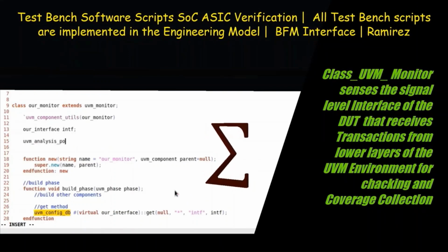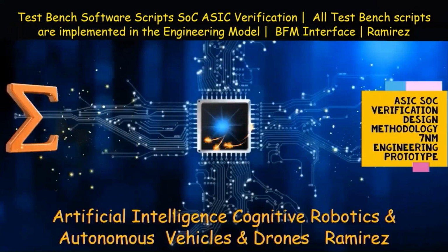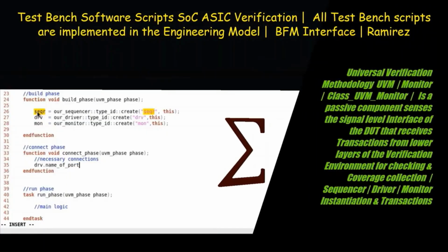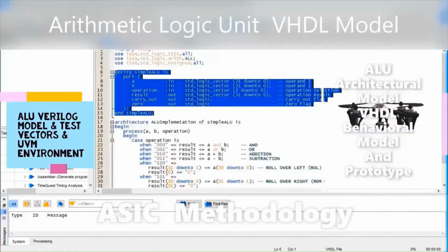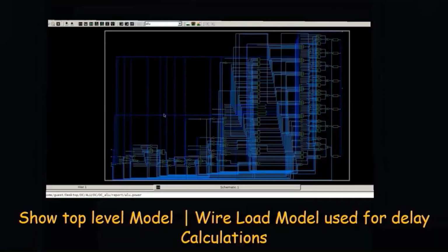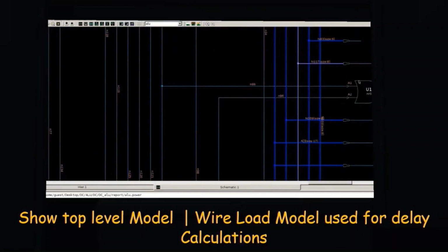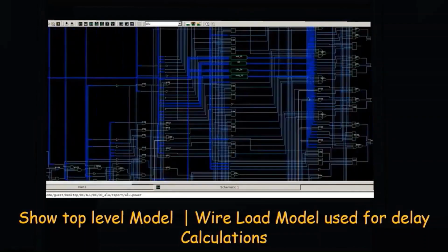that the virtual interface within the top level configuration object is set to point to the BFM interface within the test harness, that is top_hdl_th.bus_bfm_0. This is a full hierarchical reference to the interface instance of bus_bfm_0 within the top level module. So when the UVM driver and monitor proxies communicate with the code outside the class-based verification environment using local virtual interface variables, they will actually be communicating with the BFM in the synthesizable test harness.